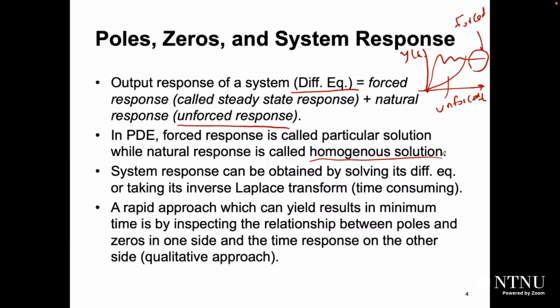So we should have a negative exponential, or a negative exponential multiplied by a sinusoidal, right? When your system is first order, it will be only a negative exponential. When it is a second order system, it will be an exponential multiplied by a sinusoidal. The sinusoidal constitutes the overshoot and undershoot, and after that the response will decay.